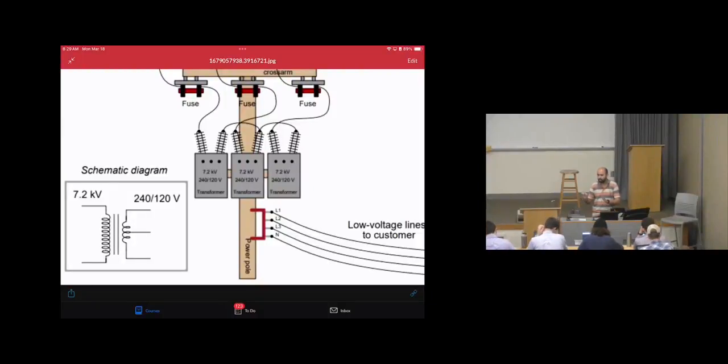Even if your homes are identical, with the same square feet, the same area, the same loads, we cannot guarantee you will consume the same amount as your neighbor. You might run the dryer and the washer, while your neighbor turns on the AC, and the other one is away from home, so the power is off. This makes a mismatch, what we call an unbalanced system, which means phase A consumption is not the same as phase B, which is not the same as phase C. This creates problems for the electrical power utility when we have unbalanced or unequal load consumption.